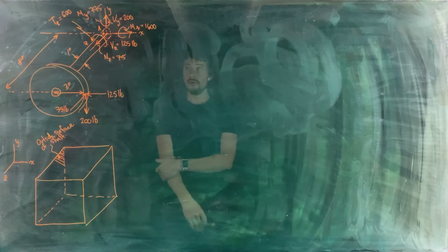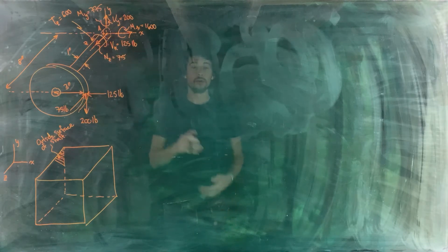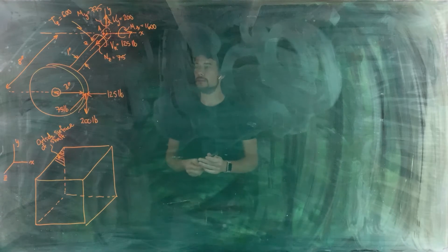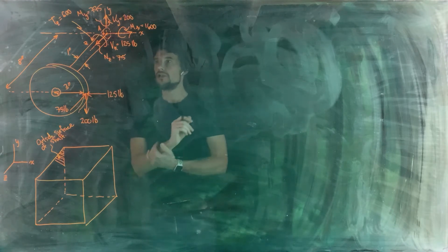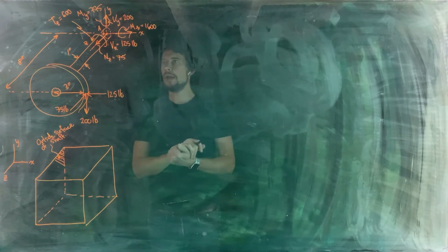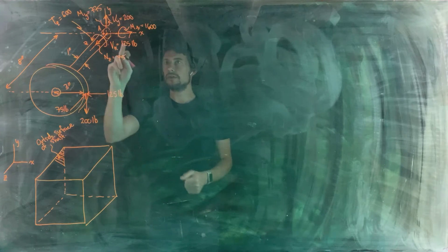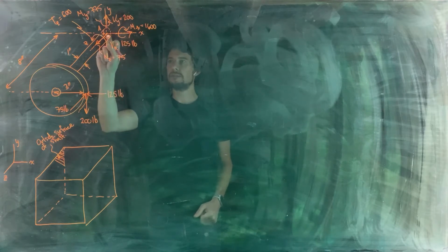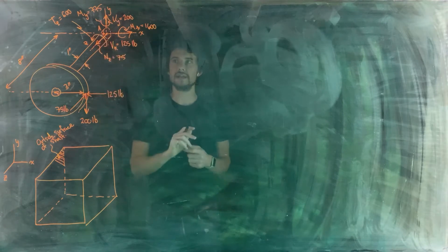All right. So let's work through the internal forces, moments, and torques in the same order, going x, y, z for the forces and then x, y, z for the moments and torques. So for our x-axis, what have we got here? We've got a shear force in the x direction, Vx equals 125 pounds. So the question is, does that create stress at point A?